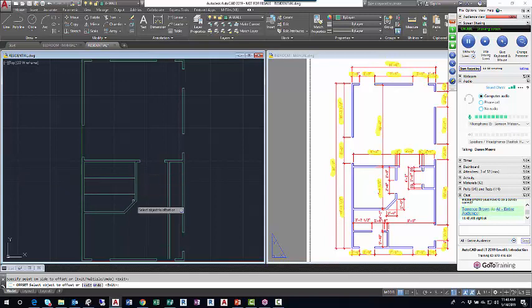I have to extend first. These 2 lines don't meet the vertical line on the outside. It would cut the inside line, but it won't cut the outside. So I'll open up where trim is, click extend, right click or press enter, and then I'll extend these 2 lines out. I've got these 2 lines extended. Now I can start my trim command. Open up where extend is, trim, right click or enter, snip, snip, snip. Just trim out these lines. Escape when I'm done. Use my highlighter.